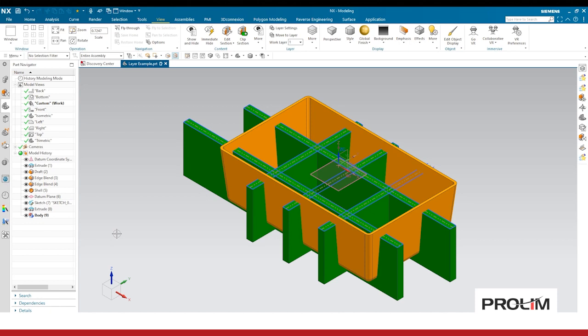But if I say wanted to hide a specific solid body in a drawing view on a model, say for instance there's some background geometry inside of an assembly that I want to hide from a specific view for a better cross section or something along those lines, you can then go into that specific model view and hide that layer that body exists on. So my solids are layers 1 through 20, I believe, if I remember correctly. And I could throw that solid body on layer 3, for instance, and hide that layer on that view.